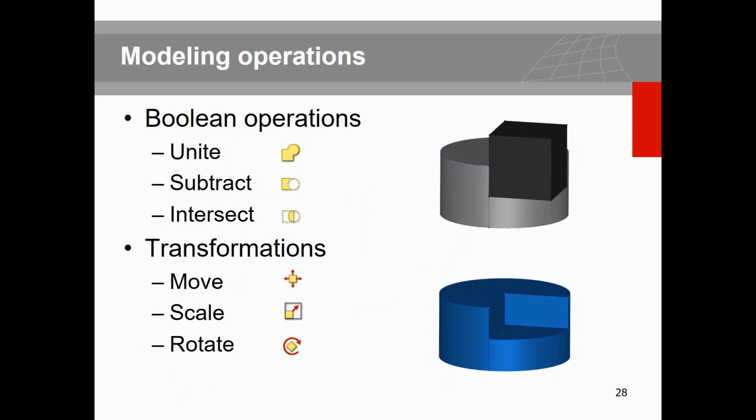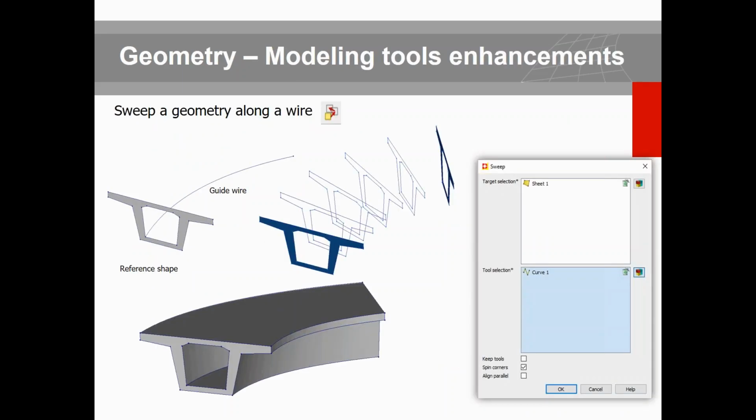Moreover, you can interact and intersect different parts based on Boolean operations, transformations, and the sweep function along a guide curve. This is very powerful because if you want to come up with a solid model and you have only one uniform cross-section, you can define your cross-section in 2D, or import this cross-section, and sweep it along the reference guide curve. Then it generates a nice solid model for you that you can easily proceed with, based on our extrusion mesher, and have a very nice and smooth element distribution along this model.